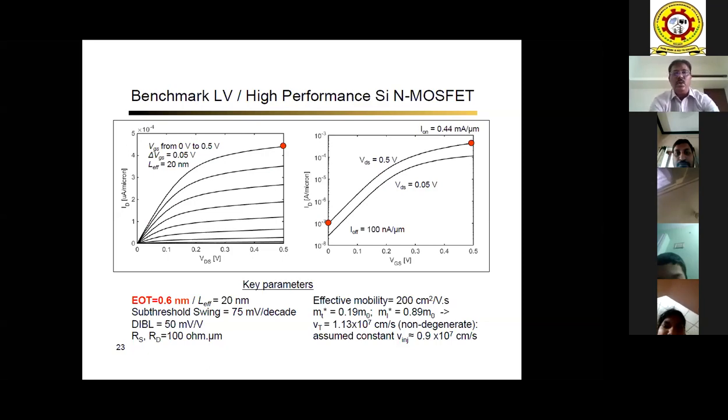If you're talking about 14 nanometer, obviously our planar silicon model doesn't function anymore because your drift diffusion model becomes obsolete. So you need to move on to either quasi quantum mechanical effects or completely ballistic, quasi ballistic or completely ballistic transport approach. Okay, that is where we are now showing the 20 nanometer model here, again with the same benchmark.